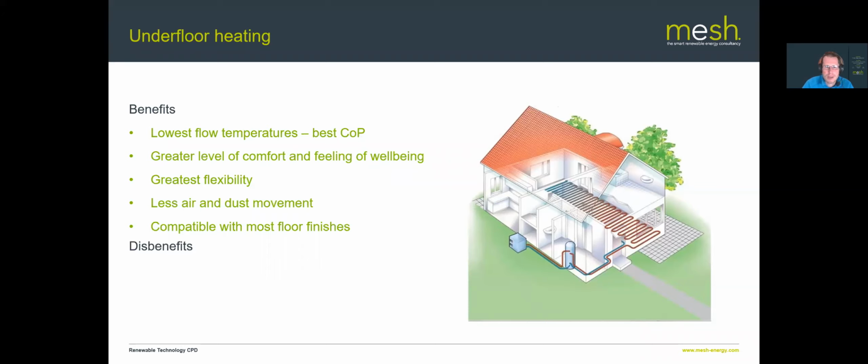So the downsides of underfloor: it is expensive to retrofit. The upfront cost on new builds is actually coming down, and although it's slightly more expensive than radiators, when you start looking into it in a bit more depth and you start specifying low flow temperature radiators for new build, it actually doesn't work out that much more expensive. So hence why I've made it quite specific to retrofit.